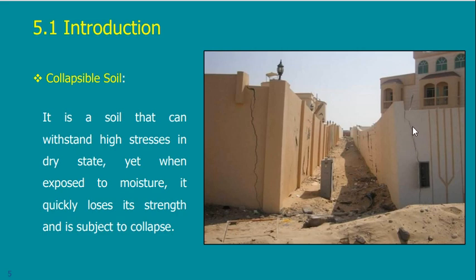These cracks happened because the soil beneath this ground is collapsible. So once they finished the building and connected the water pipes and the drainage pipes, maybe there started to be some leakage at some location. This leakage meant that water reached these layers of collapsible soil, and this collapsible soil collapsed, causing these cracks in a newly built building.